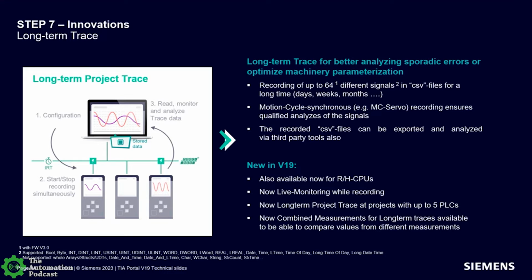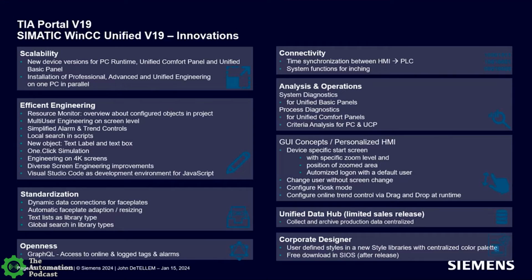user-defined configurable trace functionality. But in v18, we introduced the ability to do it without loading it in the PLC and to basically store it in a long-term format on the actual engineering environment. So I have the capability of doing a little bit more functionality or debug troubleshooting than I would if I was trying to do it inside the PLC.